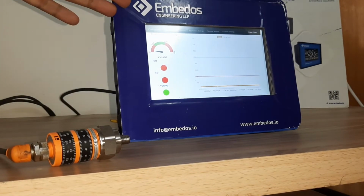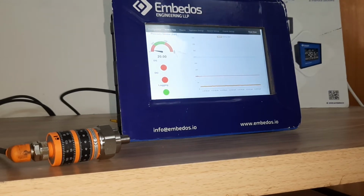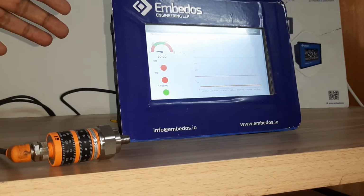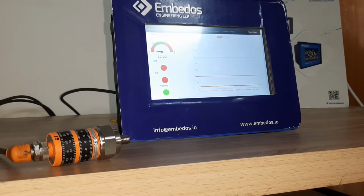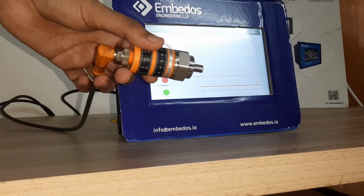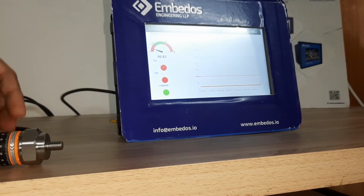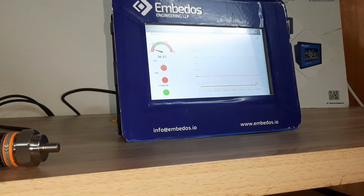This screen also has various tabs which will give you the complete information about the data that is being logged, as well as in real time you will be able to see the variations in data. The first page is real time data. We have a gauge over here to represent the variations in the data as the data increases. For this demonstration we have a vibration sensor connected behind to our analog input 4, and this is a 4 to 20 milliampere output vibration sensor. When the vibrations increase, the corresponding current will also increase, and you will be able to see it on the gauge over here.